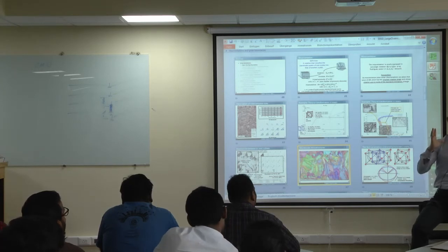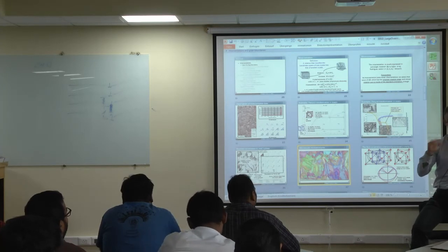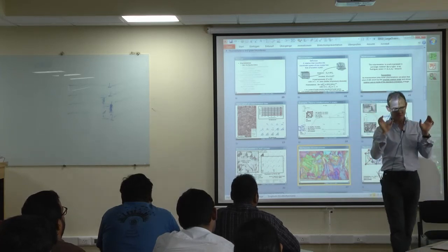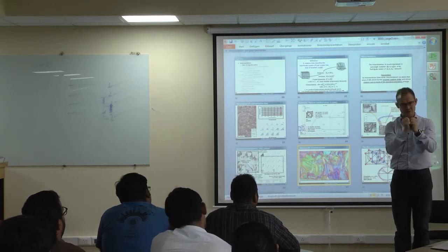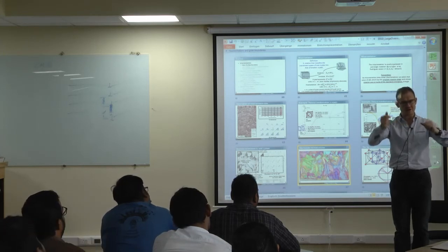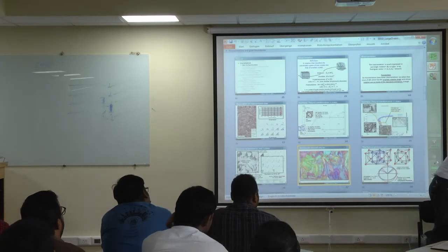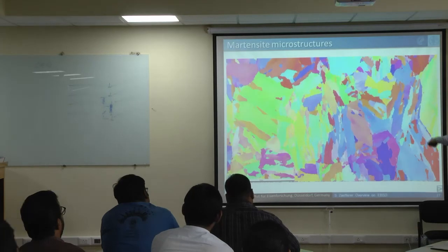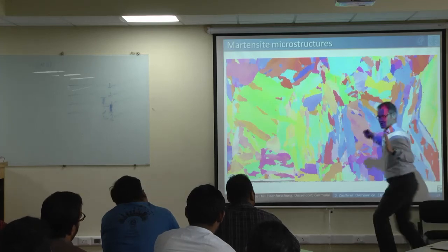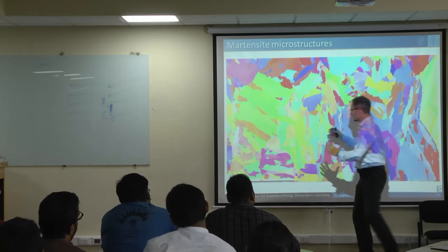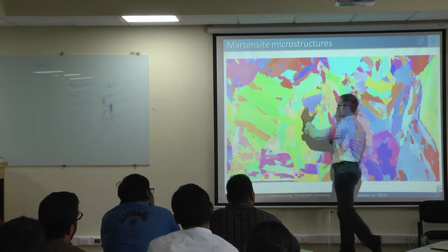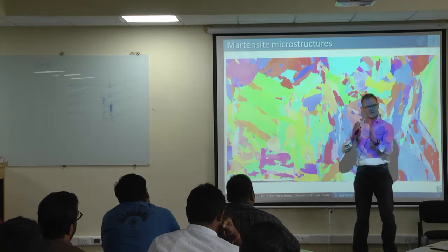And these stresses lead, depending on whether you have a hard or a soft material, you can relax these stresses or you can't. These stresses lead to the selection of different pairs of bainite or martensite variants. So when an austenite transforms into martensite, it forms many variants, as you see here on this picture. So it forms all kinds of variants. And these variants are not formed for nothing, but because during this phase transformation you have the shear and you have the volume change. And this volume change leads to the formation of very high residual stresses. And at one moment the residual stresses become so high that the variant cannot grow on. So another variant starts to compensate these stresses.